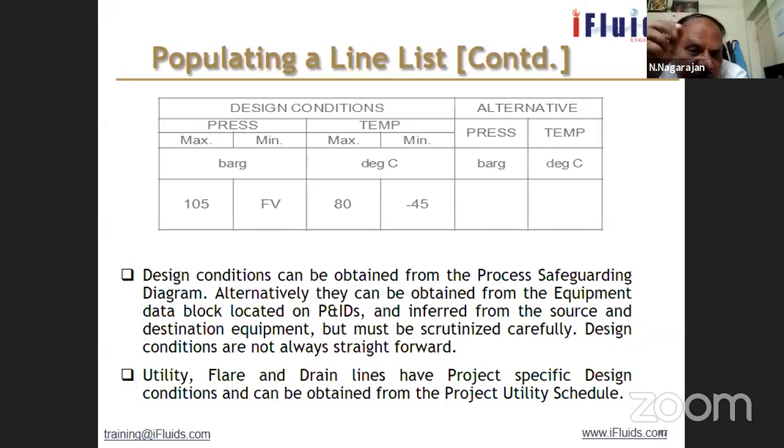That is, take the PFD and put the design pressure and temperature on each and every line and each and every equipment. Then it is called a DPDT diagram. Some companies make a DPDT diagram. For example, Foster Wheeler usually makes a DPDT diagram for all their projects.